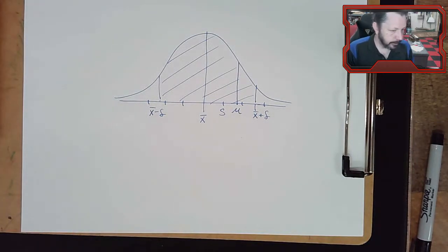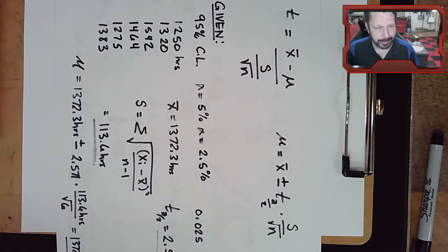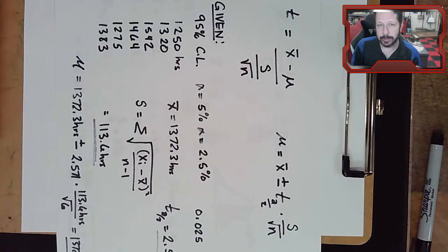We looked at the Hall effect sensor. It's super easy to implement, and it does give you a measurement of the magnetic field. I don't know if I would use it to measure a magnetic field, more the relative strength, that there is a field there or not there, and it's stronger or weaker. But there are equations on that data sheet that you can use to calculate the number of Gauss.